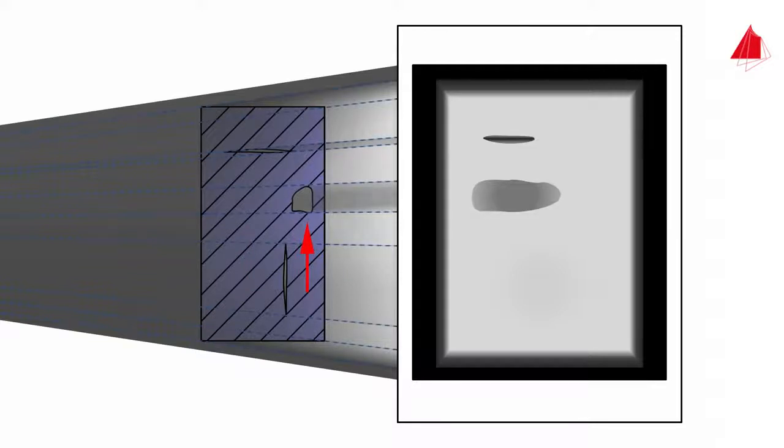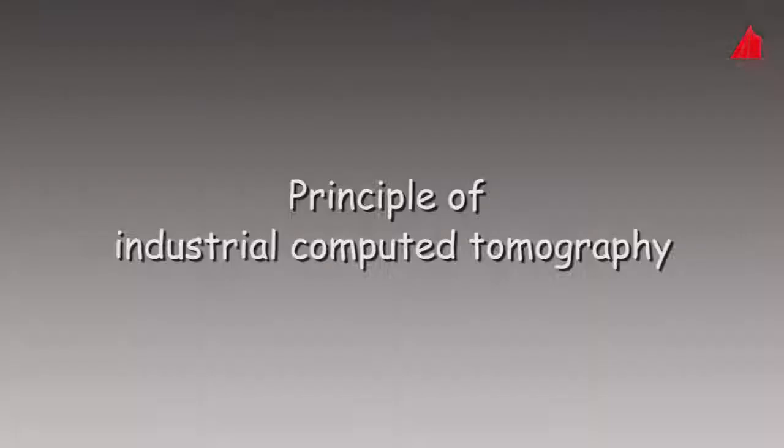In order to determine the depth of location of a defect, at least one additional X-ray image has to be taken from a different direction. Computed tomography pursues exactly this approach, not only by taking one, but in fact many additional images. A fantastic method. How does it work?